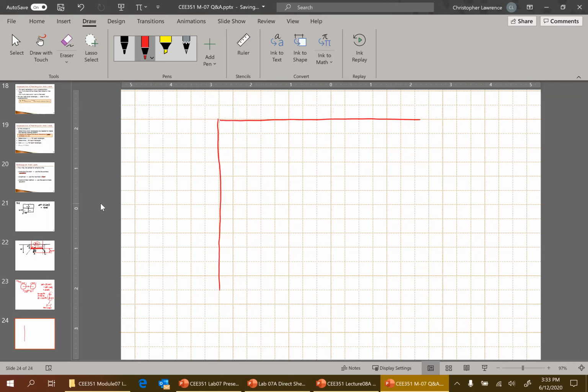It's talking about the center of a square versus the center of a strip load. So I would say Z is the depth, and I want to plot Z downwards because it's depth. And this is then my sigma. When Z equals 0, then I equals infinity, and so you just get sigma equals Q for the square.